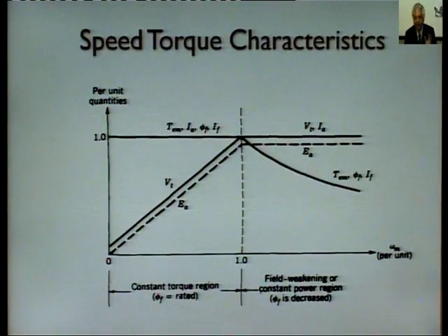So, if you increase the armature voltage, the speed is going to increase, and if you decrease the armature voltage, the speed will decrease. It is directly proportional. But the reverse is the case for the field flux or field control method, where the flux is inversely proportional to speed. If you want to increase the speed, you have to decrease the flux, and as you all know, flux is related to the field current. If I want to change the flux, I have to change the field current.